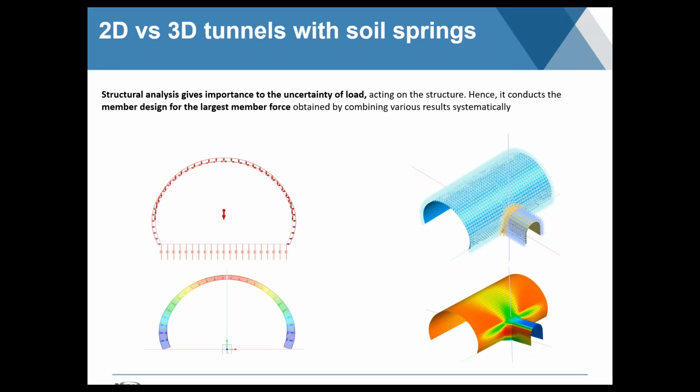So last time we've been talking about the different methods for analyzing tunnels, for designing tunnels. One point of view is from the structural side, where you can use springs to model the behavior of the soil, approximate the linear behavior of the soil, and you basically end up just applying loads to the tunnel and, based on the stresses, based on the demands from the members, you can more or less determine what the shape and the lining thickness would be. And you can get a decent approximation by this method. It's relatively simple.